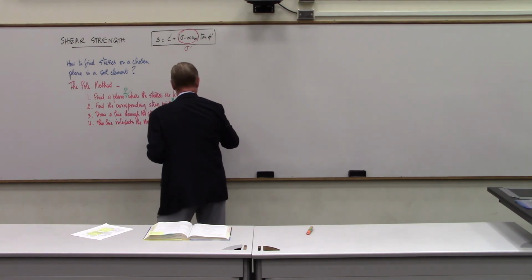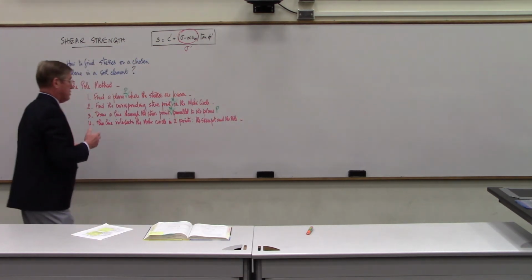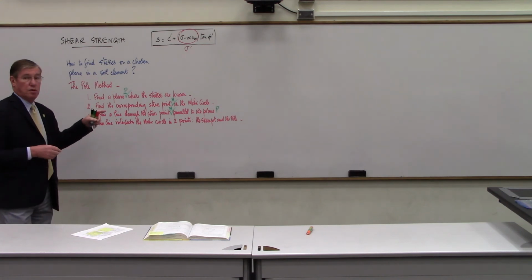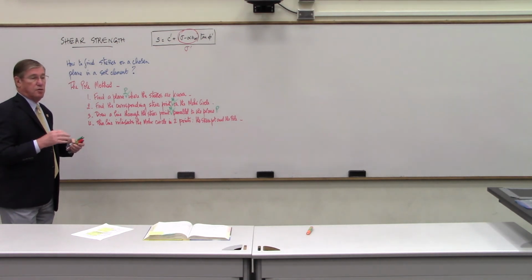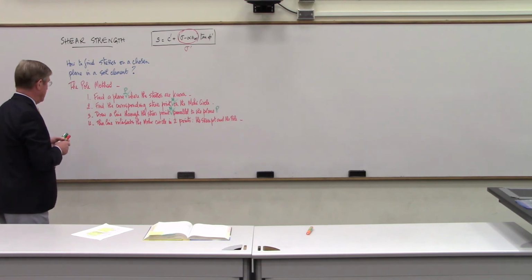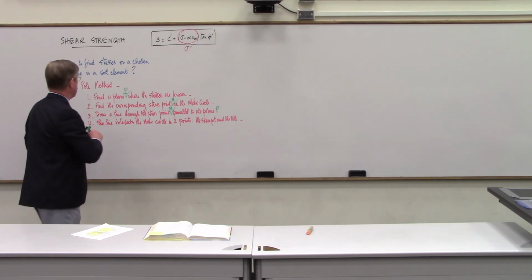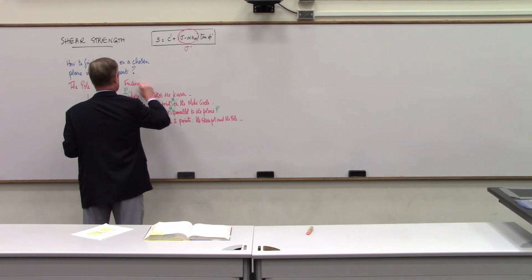The stress point and the pole. Okay? Well, that's the property of the pole. Now this pole is a unique point on the Mohr circle. The plane can change, the pole doesn't. So once you found the pole, then you know where it is. It's not going to change. So that's how you find the pole.